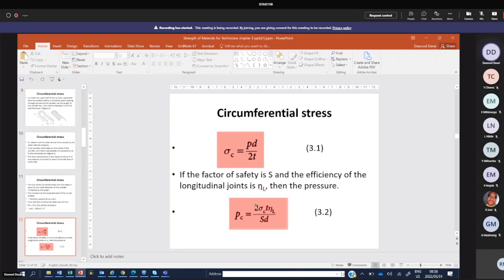Right, so there's your two formulas again. So stress circumferential. Remember, the circumference is a small one, so it could be PD upon 2T. That's how you remember it easily. Now, remember, these type of pressure vessels are governed by design codes. You don't just design these things. There's a whole code of practice because it is a critical item.